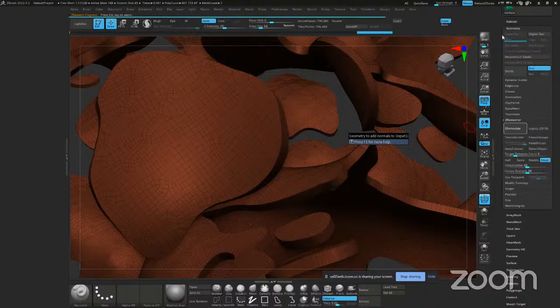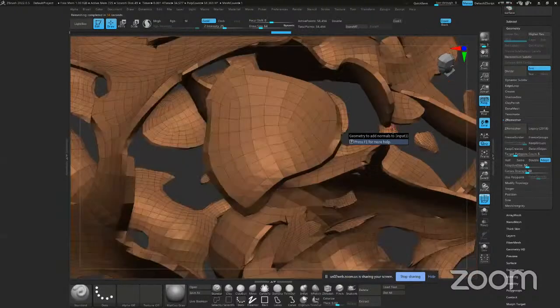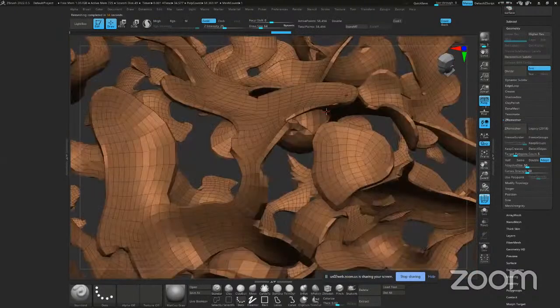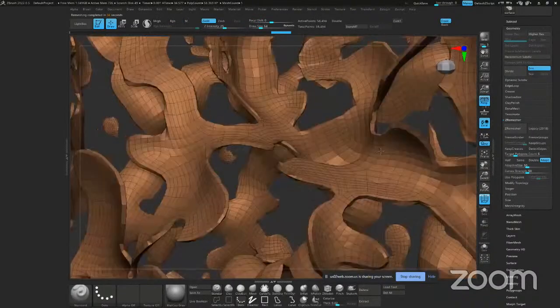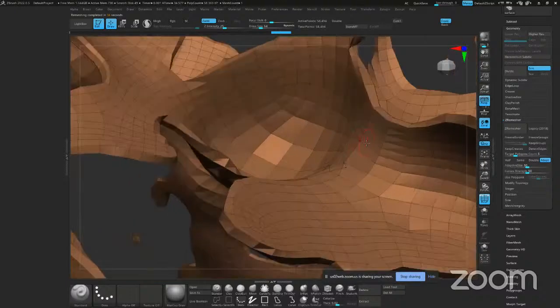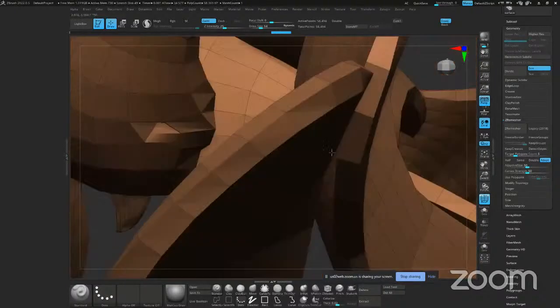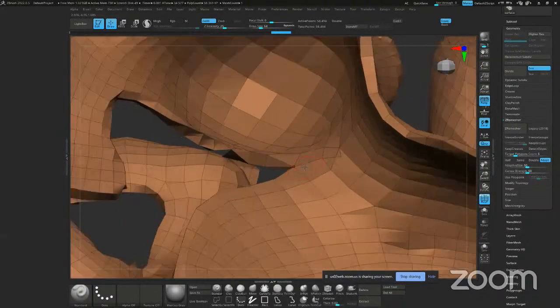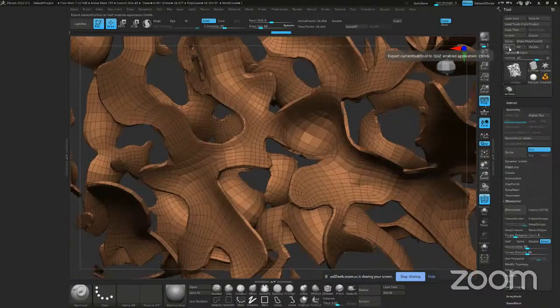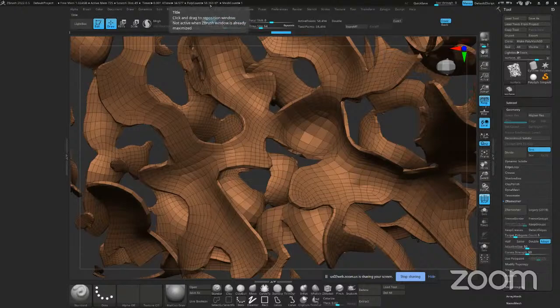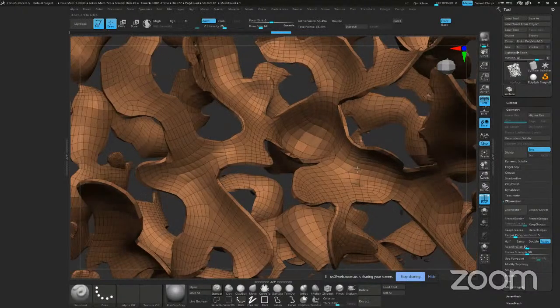But at the end, this particular way of interacting with geometry between Houdini and ZBrush, I think it's amazing. It broke everything. I mean, the mesh is smooth and it's respecting the curvature, but in some places it has messed up. We'll have to play with the settings. Right now you are dealing with 58,000 points. I think that's too few for that particular geometry. You should increase the amount of points. But yeah, it's looking better.